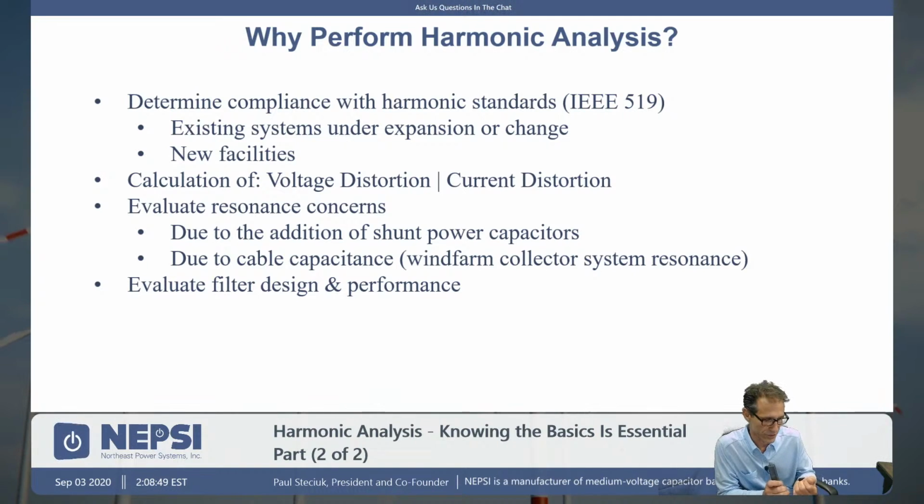So what is the voltage distortion? What is the current distortion? And really, when you are doing harmonic studies inside the plant, voltage distortion is the key area of concern. Remember, we're typically designing for 5% VTHD inside the plant.